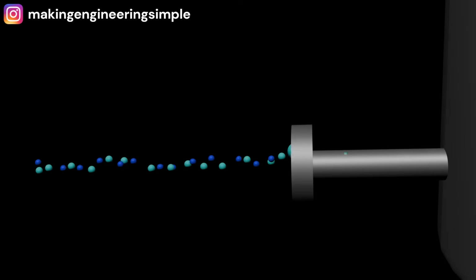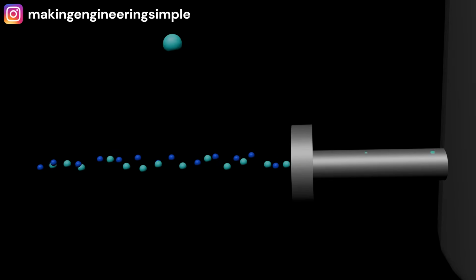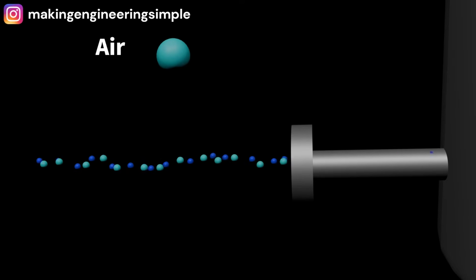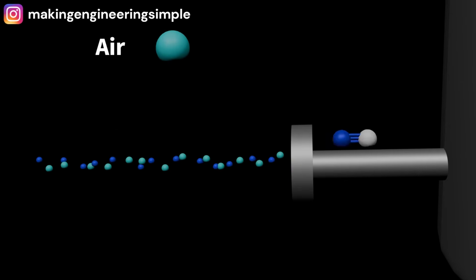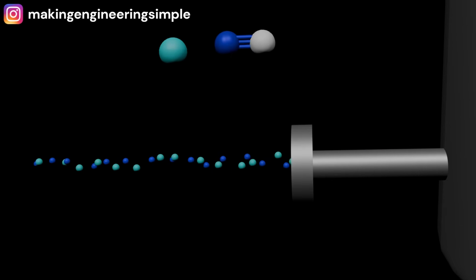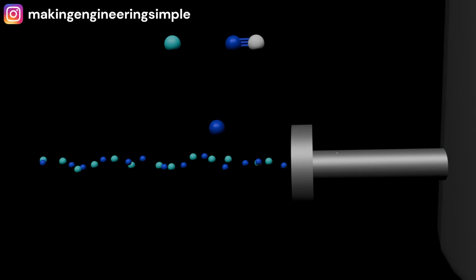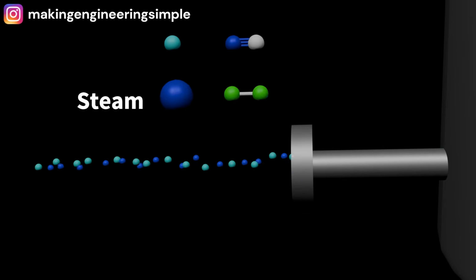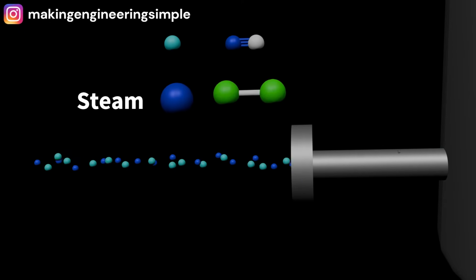In order to create the fluidization of the bed, a mixture of air and steam is used at high velocity. Air provides the oxygen necessary for the partial or incomplete combustion to produce carbon monoxide. Steam reacts with the char and other components to produce further hydrogen and carbon monoxide.